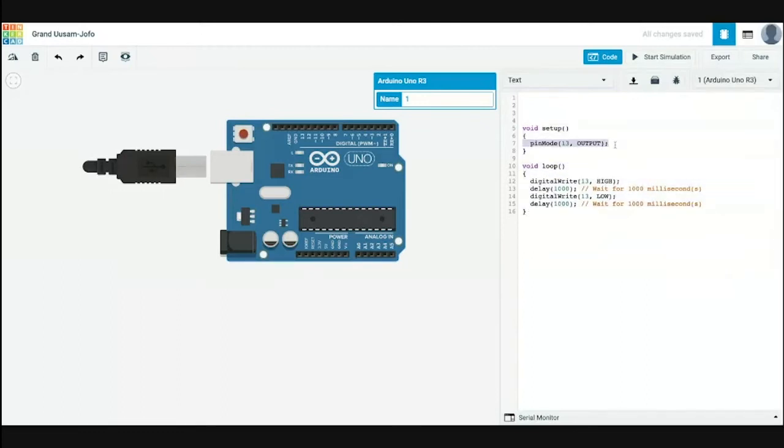On this command on line 7, we can see that pin mode is the command that is called. It is being told that on pin 13, it's going to pass an output signal. That means that electricity is sent out from that pin. But wait a second, there's nothing plugged into pin 13. Well, we can actually tell from this example that pin 13 and the onboard LED share an electrical path. Whatever is done to one will affect the other because they are connected.